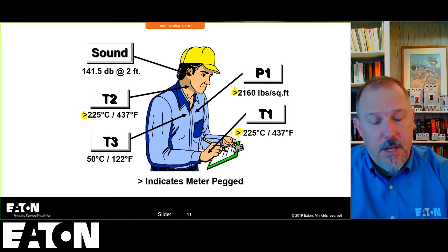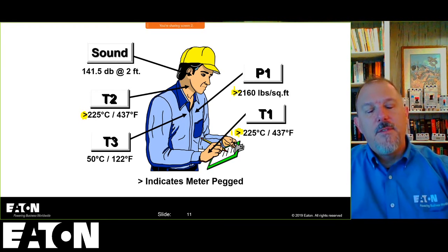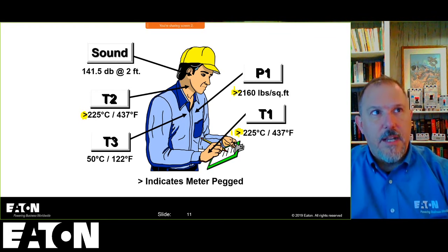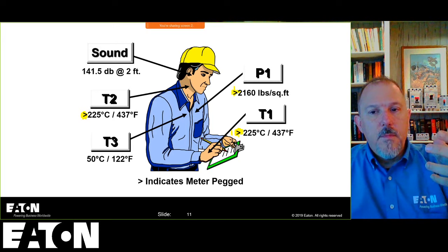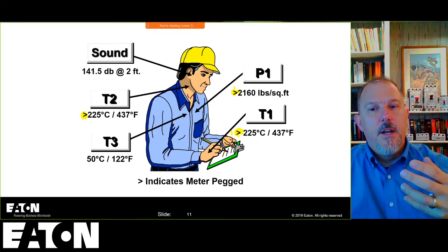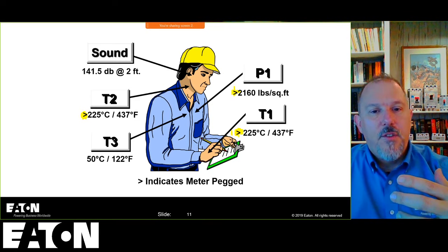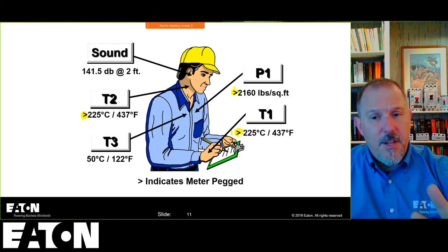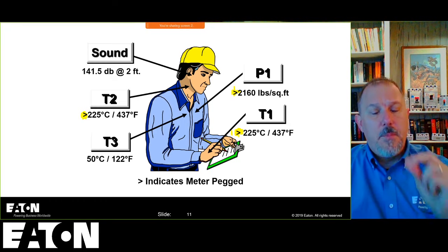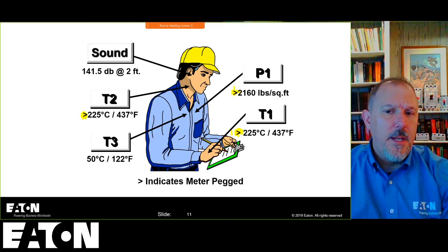Now, the next video I'm going to show you has a smaller overcurrent protective device that's going to be a couple cycles to show you the magnitude of what that current limitation does, or the current limiting device does, to reduce the amount of energy that the electrical worker is exposed to. So there's going to be 3 videos in here. The second one is going to be a smaller incident energy because I have a smaller overcurrent device in series with it. And here it goes.